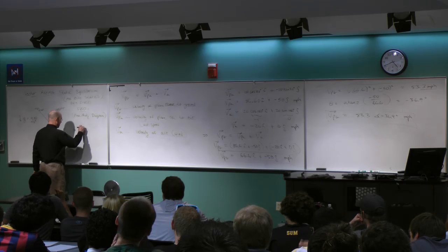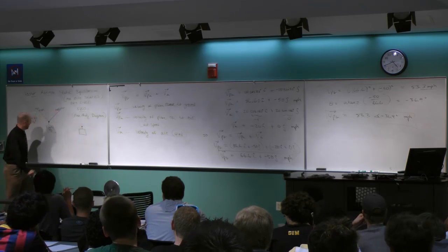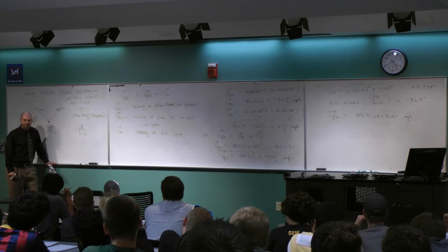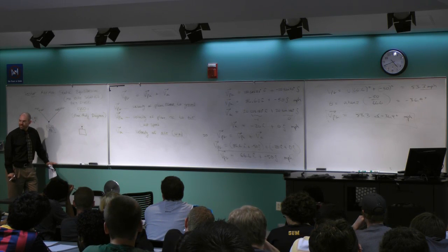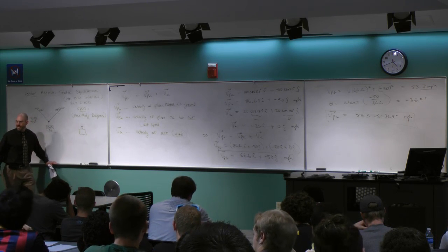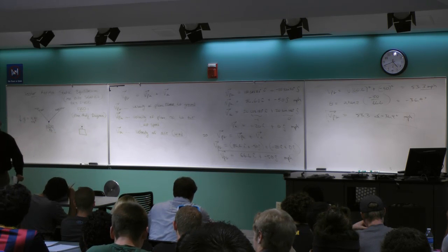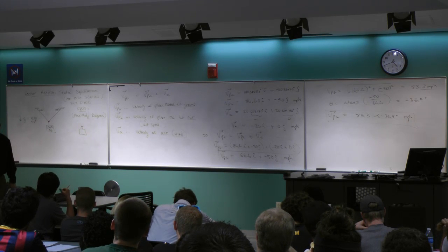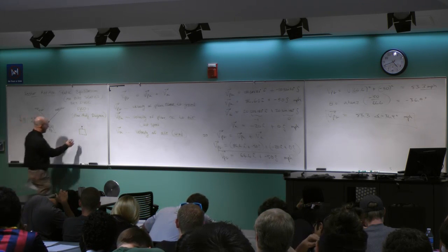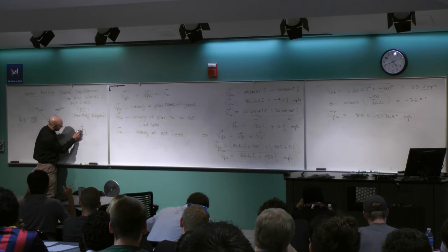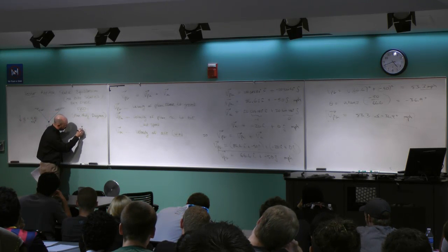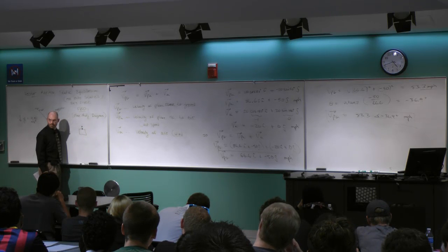So let's say I want this to be my free body diagram. It's going to be the block right here and also this little joint right there. So free body diagram, you can isolate any piece of any physical object, and if that object's in equilibrium, then the forces acting on that piece have to add up to be 0. Okay, but the thing is this rope connected right here to the block? So do I got to put a force here where the connection is? Because isn't there a force there?